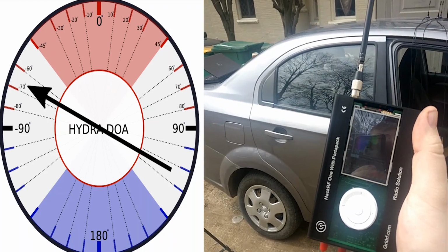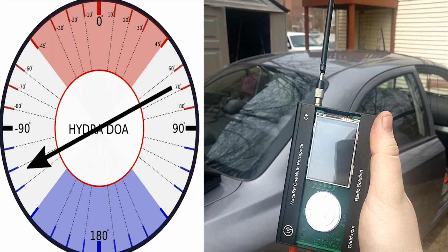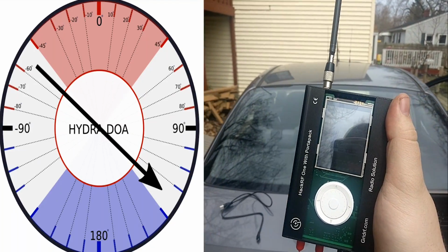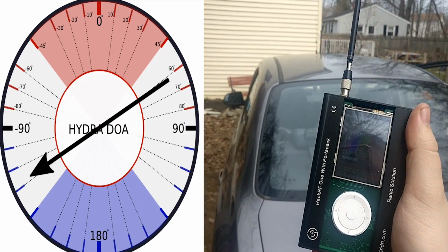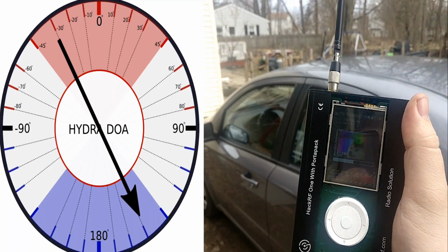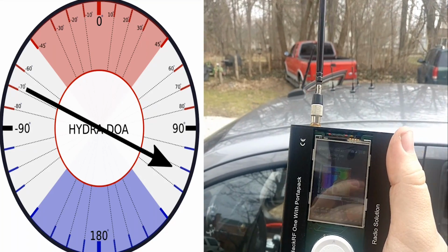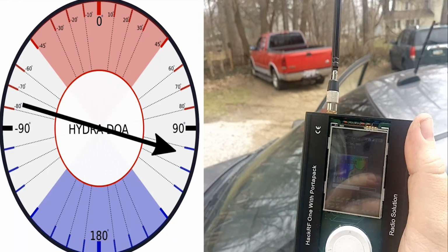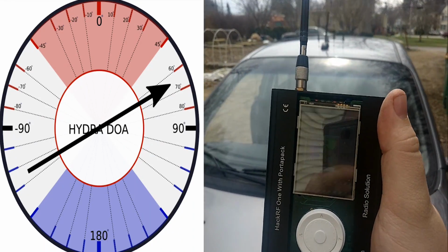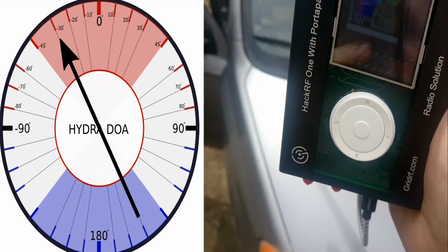The purpose here is to show you that we can now see a full 180-degree view. Unlike a linear array, this can tell us whether a signal is behind our vehicle or in front of our vehicle. That being said, you do see that the needle jumps around a bit more than it did with a linear array, and that is mostly due to multipath interference. Our signals are bouncing off other objects, and it is somewhat skewing the results. However, there are pros and cons to using a circular array. If you're just getting started, I would highly recommend you start with a linear array for simplicity.